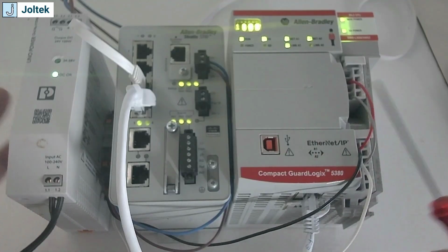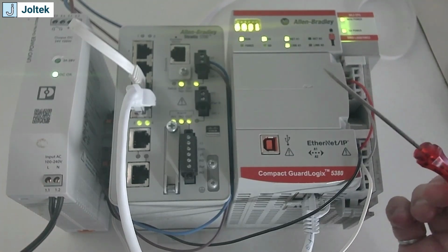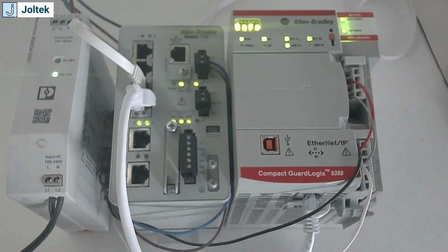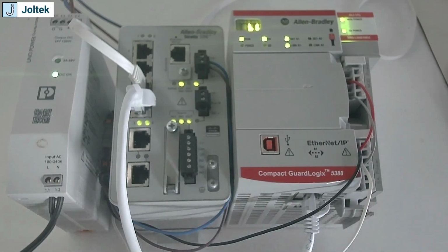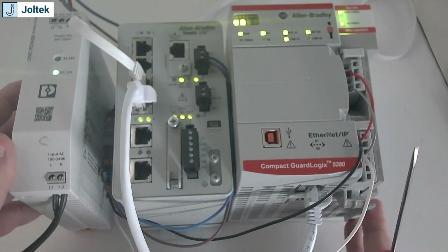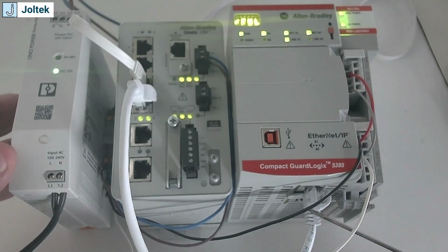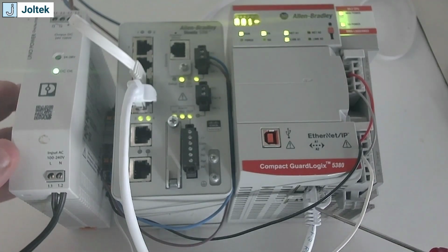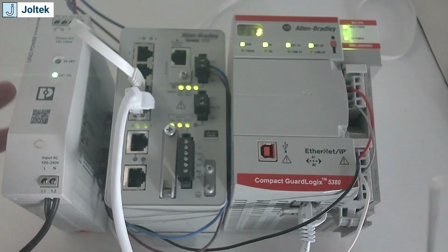When it comes to the actual hardware, we obviously need a PLC to run RSLogix or Studio 5000. In this case, I'm running a fairly recent model of a safety version of a CompactLogix PLC, and I have two different Ethernet ports. Again, this is part of the OT networking course, so we're going to talk about this really briefly. In this specific model of PLCs, you have two different ports, and I may have mentioned this in the past, but you can configure each port separately. So it is important to pay attention as to where you're plugging in, if you're looking to program the PLC, if it's going to a plant network, or if it's going to be talking to the switch.